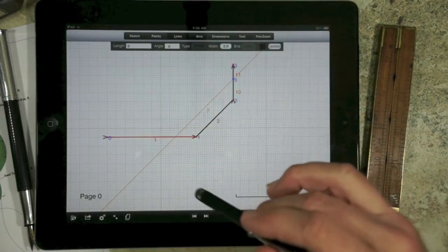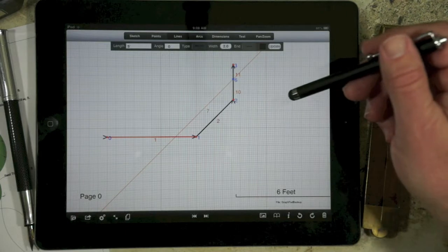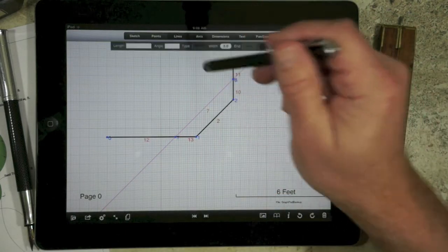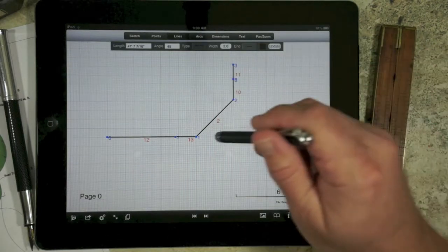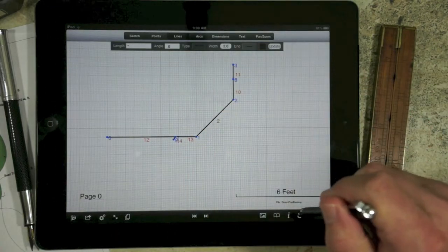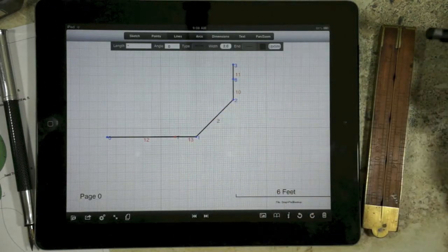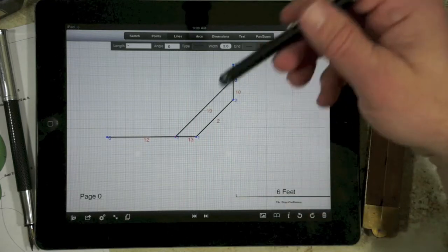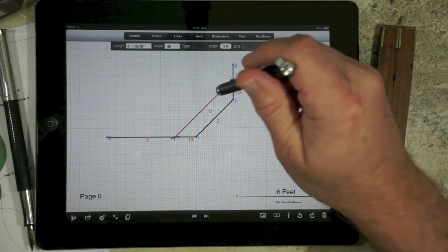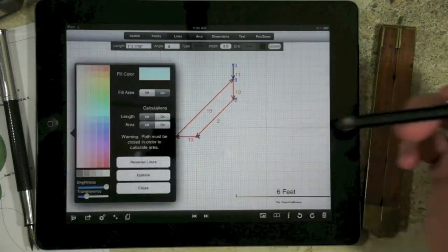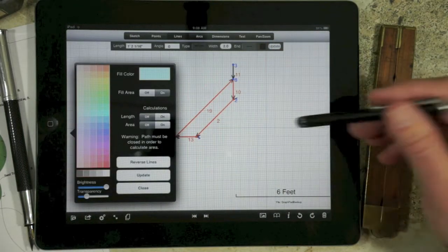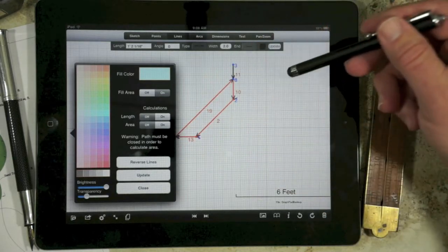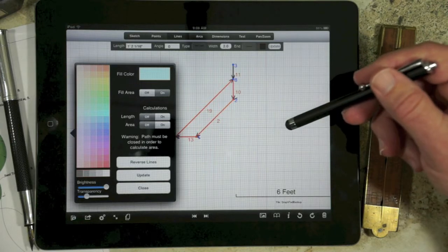So to fill out this geometry, all we would have to do is, in lines mode, select line 1, we have line 7 selected still, hit points, it broke that line, and now go back to lines mode, delete this one line, select point 7, notice I wasn't quite close enough, select point 7 which is highlighted, select point 8, and then it creates line 19, and now we can select the lines around our perimeter. You'll notice that we see arrows that show the direction of the lines. You see this is a closed geometry.